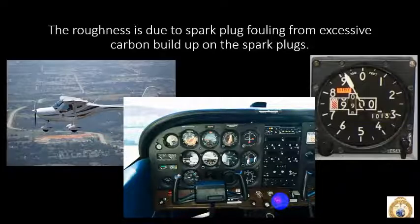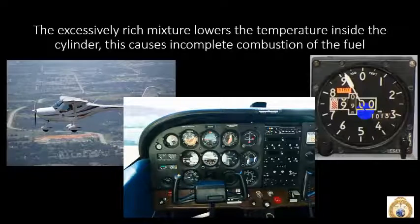So, like we said, if you go up with your mixture too rich, which means you're putting in too much fuel and you're not reducing your fuel for the reduced amount of air at high altitudes, and this altimeter is showing 9,900 feet, you're going to have an excessive carbon buildup on your spark plugs. All you have to do is lean your mixture, but not too much. Okay, because the excessively rich mixture, well, they're saying it lowers the temperature, and we talked about the carbon